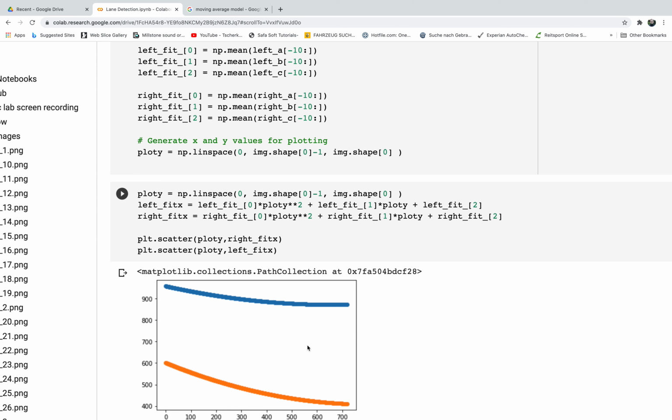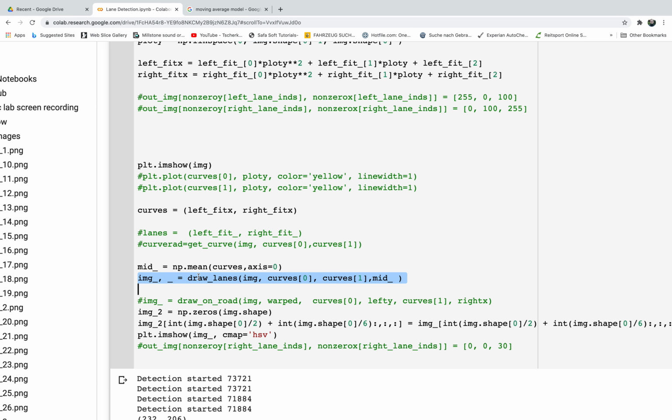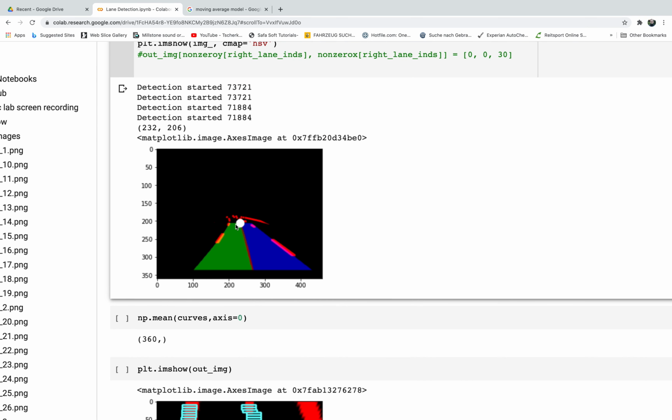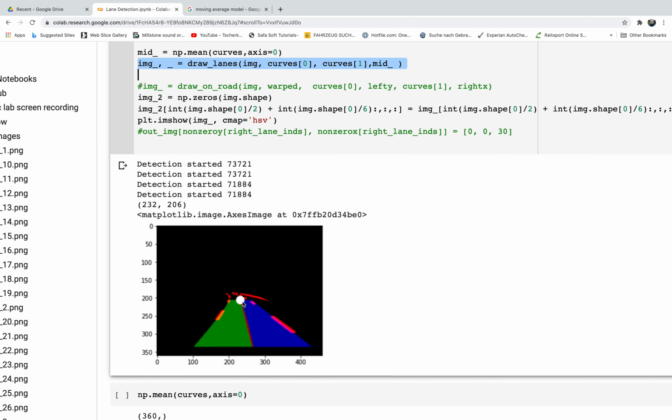What I will explain in the next session is how to draw all these three lanes or three curves. I'll also draw something else, which is the target point, which is the end point of the middle curve. By doing that, we can get these target points. We can use these target points for our controller, let's say our pure pursuit controller, or also the PID controller that Carla has, that I presented in the second session of Carla simulations.